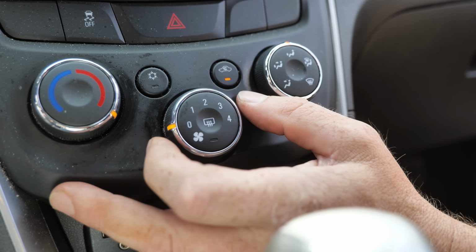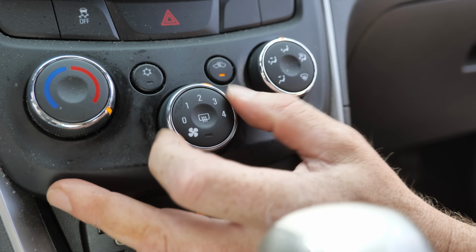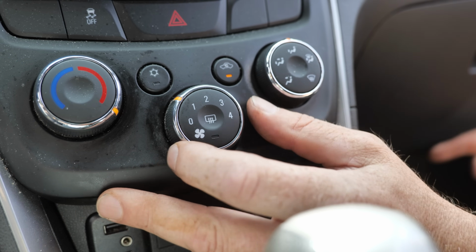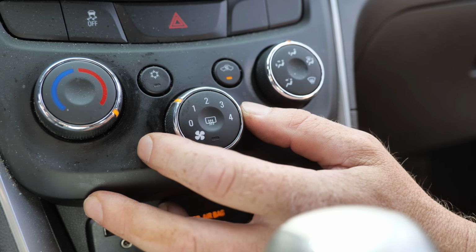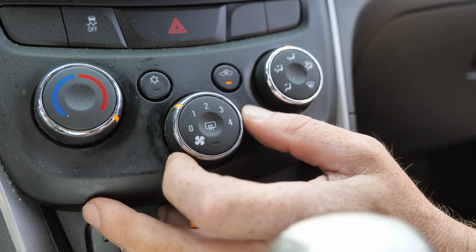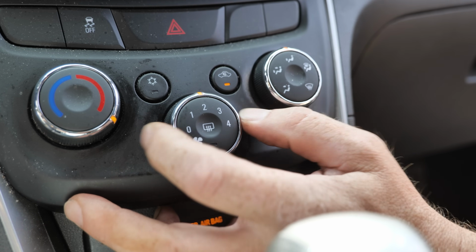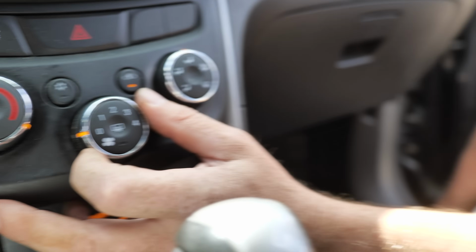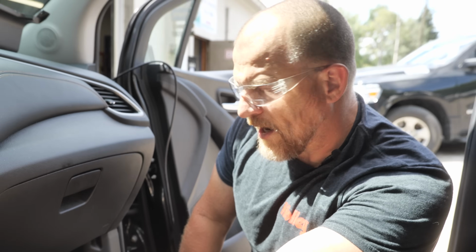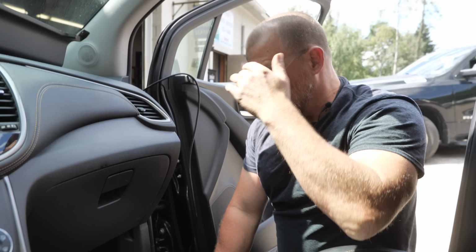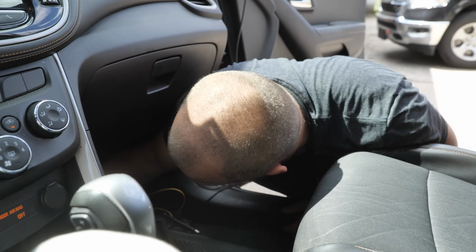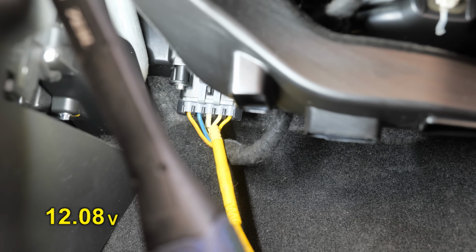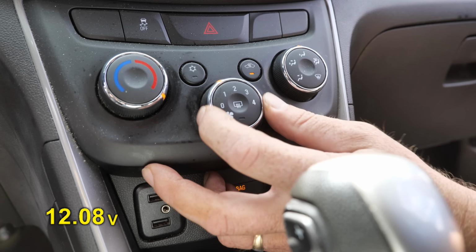But I believe what we're seeing voltage-wise here, that the reason it's low on all of these is we're never passing the current flow for the blower through this because we have a burnt connector between the 2 white-blacks. And so it's just basically grounding, and that's why you're not seeing that voltage drop that I just described. Now, the question for us then is, did I do the first white-black wire correctly? We know the blower works. But did I measure the first black-white wire correctly? So I'm going back to it. 12 volts on that guy. I just moved it over 1 pin, redoing this check. You're going to see this is going to stay at 12 volts the whole time.